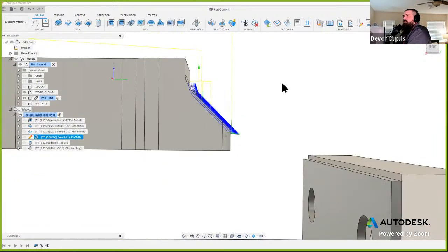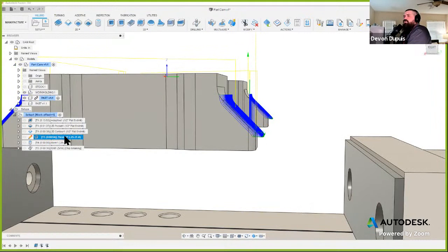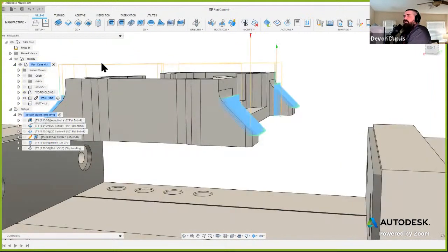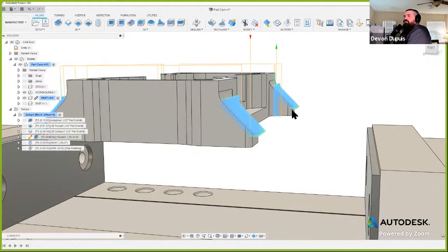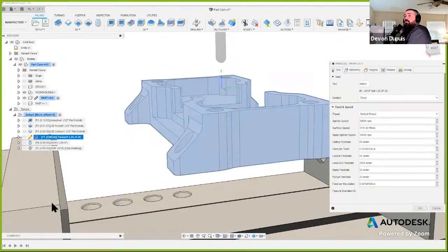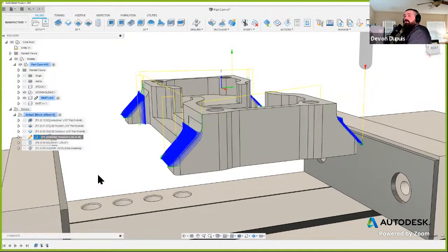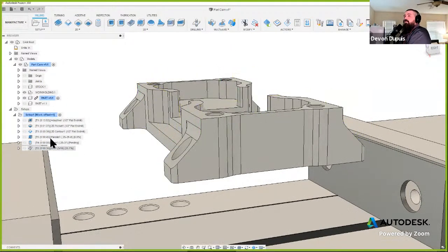I see there's maybe some other areas here that I might want to adjust. Let's go ahead and try to make this toolpath the way I would normally do it, to get a little bit better selection here. And this honestly might work. We delete these. So we can right click on this, go down here and hit delete. And click delete again. If you have one, there's a discard edits dialog there.